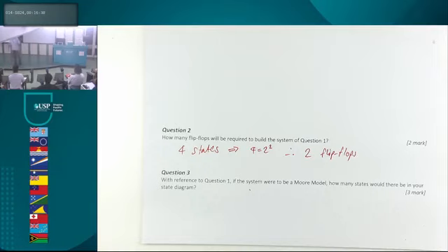Sometimes you will find solutions where they are doing 3 bits but taking 4 states to do 3 bits. That is an unminimized solution. If you build the circuit, it will still work, but the difference is it is not a minimized solution. That's what I'm trying to say over here. And if you have 3 bits, generally you should be able to accomplish it in 3 states.